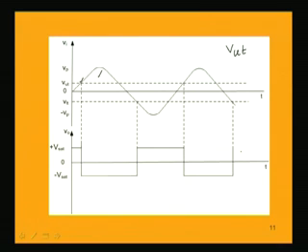So, basically here we have seen one interesting aspect, that the output voltage is a perfectly square wave, and we have the output voltage versus input voltage. If we consider it, we find a hysteresis, and that is shown here.